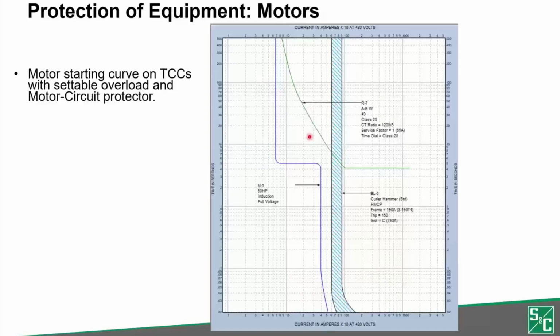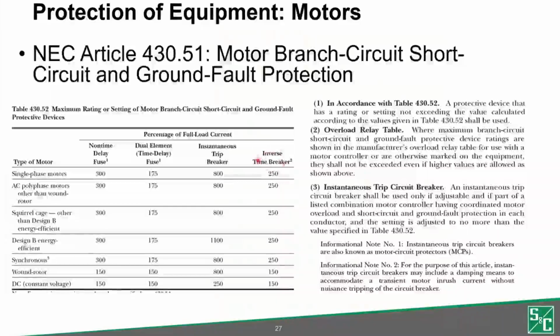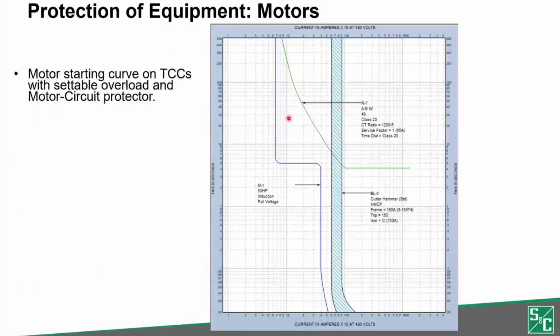Now this curve, this protection device here isn't a typical inverse time breaker as we talked about on here, but back to here, what we have here is kind of indicative of a combination motor starter. So your motor starter is not a protective device, and so that just would turn your motor on or off, and it'd be full voltage or reversing or something like that. The protection doesn't really matter that much for that, but you have two devices that are protection.